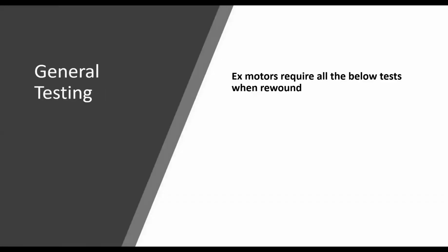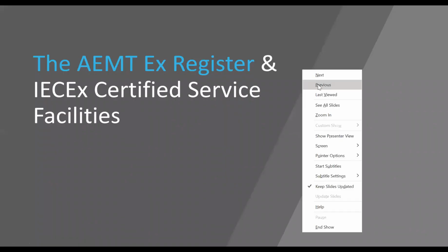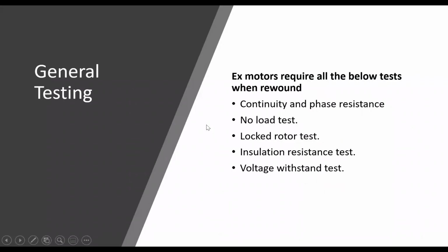So general testing, when any EX motor is rewound, the following tests need to be performed. Now, continuity and phase resistance, fairly straightforward and simple. No load test, you're putting the motor on a bed and you're running it up to full voltage, checking the speed, making sure there's no vibration.